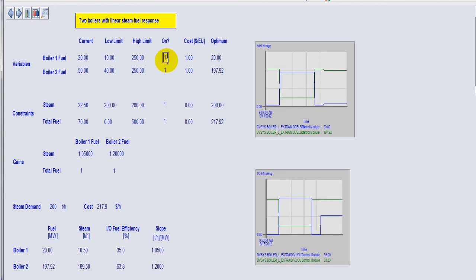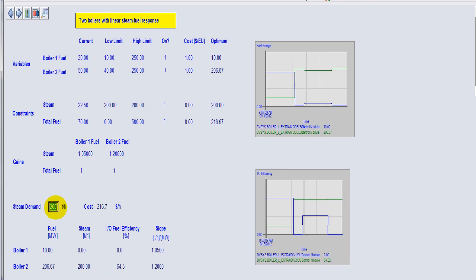So we'll now put both boilers online, and let's look at the way steam is allocated as the load changes. We've seen what happens when one boiler is taken offline; we're shifting the total demand to the boiler that's still online. As we change the total steam demand to a very small number, we see that the total load is taken up by boiler 2, the one with the highest incremental efficiency. As the demand goes up, we still use the boiler with the highest incremental efficiency in taking the total change in steam demand.